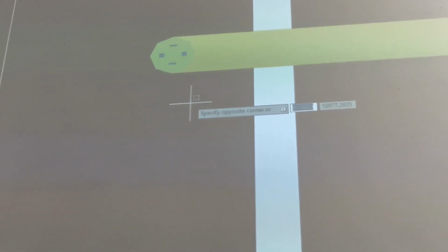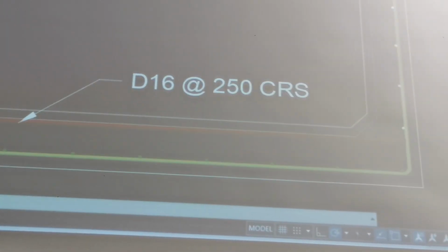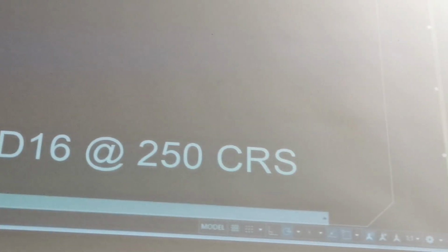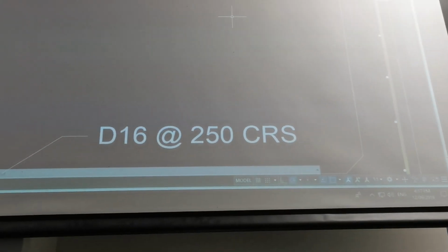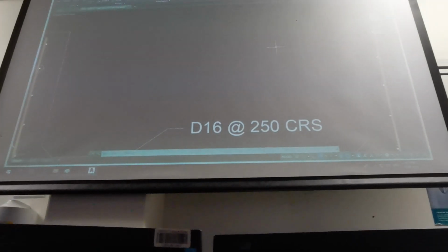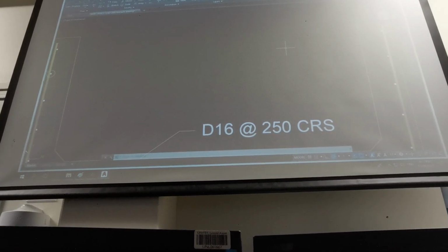Now I'm not making you do it for assignment 1, but on assignment 2, I expect that you'll show the elevational view. So on assignment 2, I would expect that you'll show the bit at the bottom with the reinforcing, because it's not a proper set of structural reinforced concrete drawings if you don't show 2 views, because you can't work out what those donuts are all about.